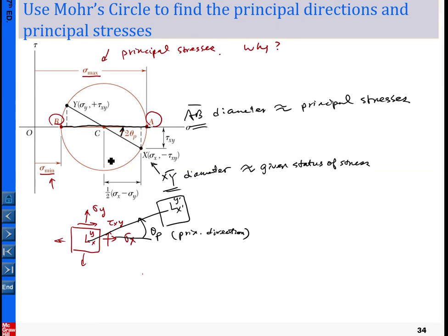Okay, and there is a profound explanation, but at this moment you simply take it: in the original transformation of the coordinate system, we take 1 theta, and on the Mohr circle we take 2 theta. Again, any angle rotation on the Mohr circle is twice the amount of the rotation between the coordinate systems.